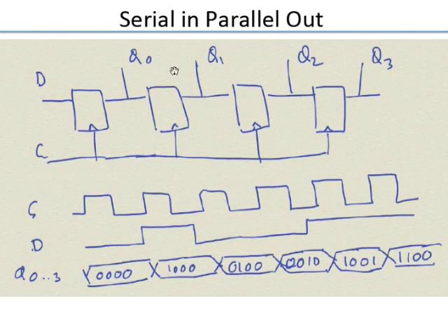Now these test patterns are introduced in the serial fashion. You have a shift register where you just shift in the test pattern, then this becomes the input to your combinational logic block, which gets tested. Similarly, at the output of the combinational logic block, the parallel outputs are captured in a register and shifted out serially. So now you just have a single extra pin through which you can put in all your test patterns and take it out. Things are a little bit more complicated, but basically this is the main idea of shifting in serially and taking out, essentially to reduce the pin count. Okay.